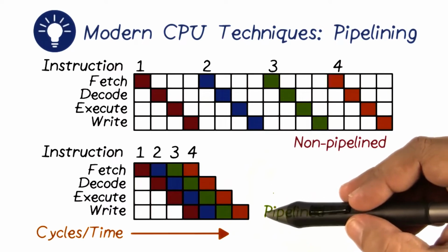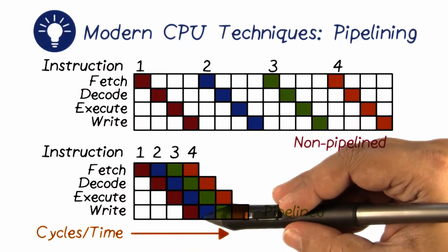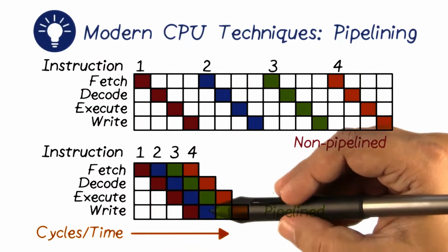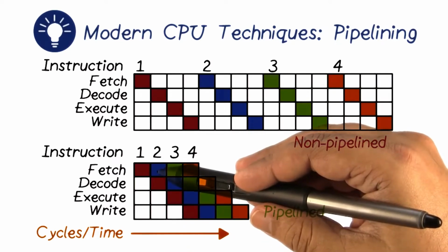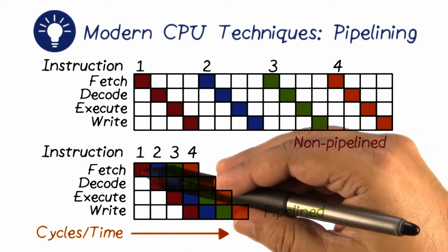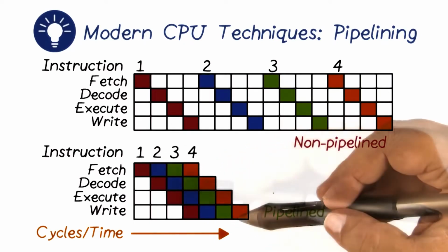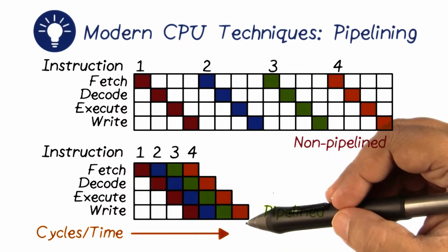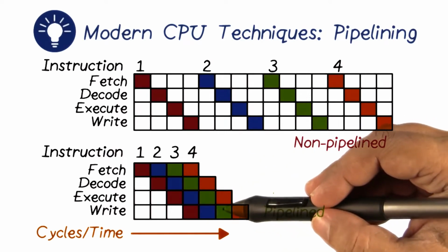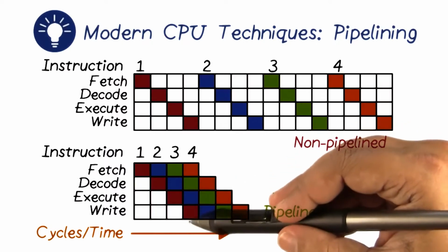Each instruction goes through several execution stages. Each execution stage has a resource associated with it. A later instruction can share the resource which is used by the previous operation in a previous cycle. Like for example, this second instruction over here is sharing the resource of fetch, which is used by number 1 in the previous cycle, and so on. A given instruction streams through a pipeline and goes through k execution stages for k stage pipeline, taking k cycles to come out. Thus, in a given cycle, each stage of the pipeline is occupied by different instructions, and thus the instructions overlap during their execution.